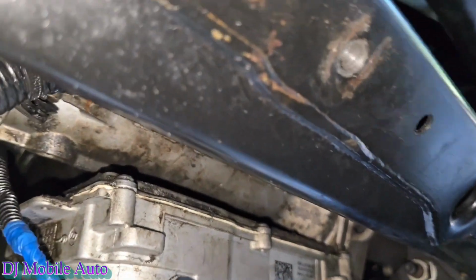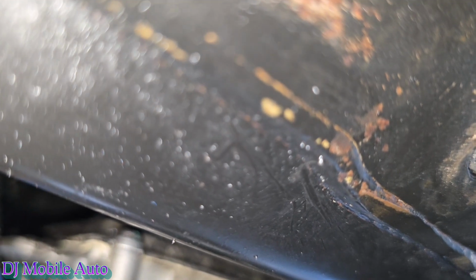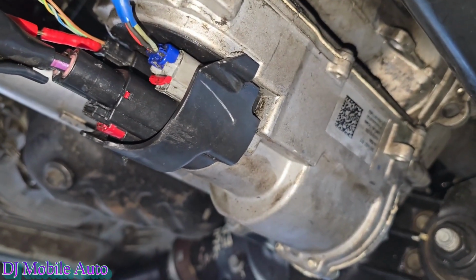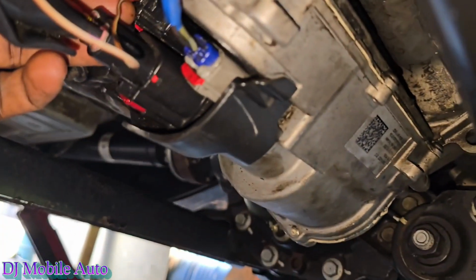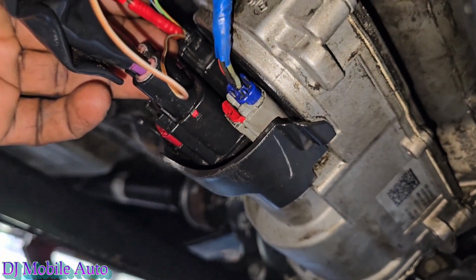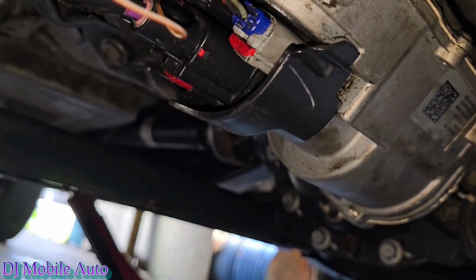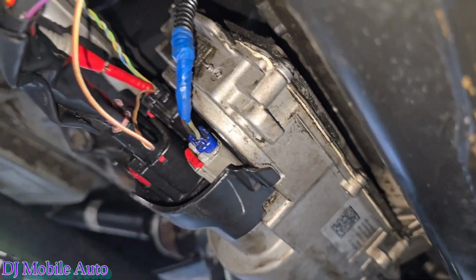So let me see if I can get this last wire right here. Okay, and just let me know that all is well, and I'm gonna make my call and let the customer know what they need to do next. Yeah, as I said, man, I'm kind of trying to hold the camera and get that wire in. Okay, so I got 2.7 right here, right? That's on the green wire with the orange stripe. So that let me know that that's my CAN high, I believe. Okay, right on the medium CAN speed. So that lets me know that my communication is good, right?